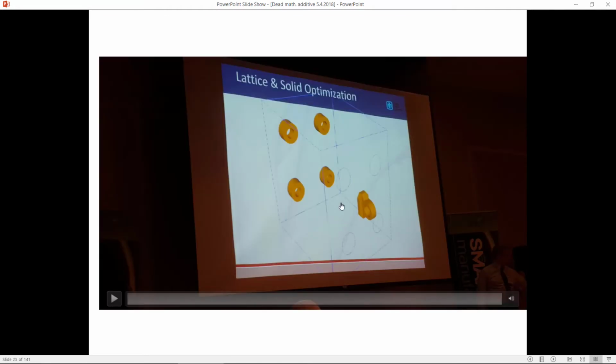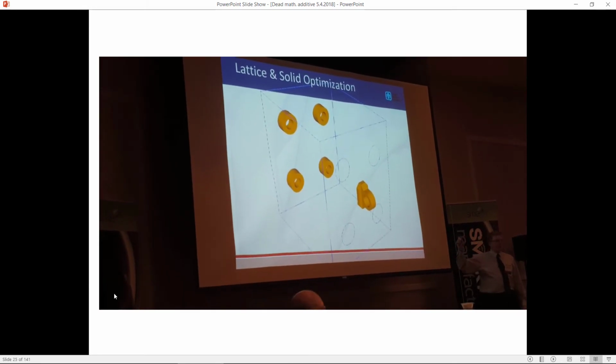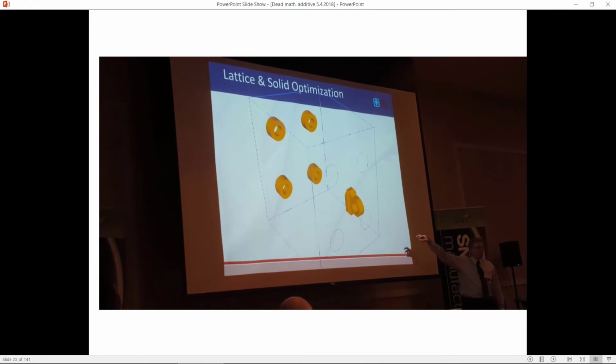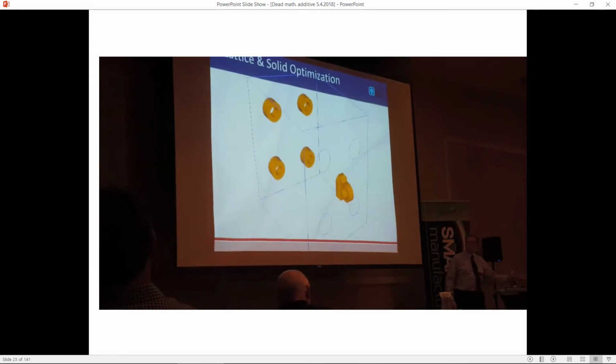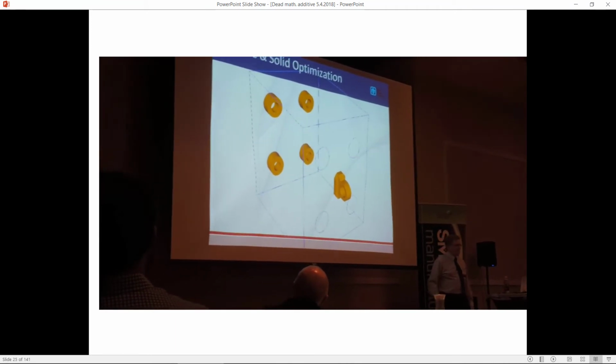So here's an example. If we need a bracket that mounts up in these 4 spots and also has this support that has a load base on it, what should this bracket look like? You set all this up, you set the material up, you set the load condition up, and then you hit optimize. Now, I don't know if you can hear this gentleman speak, but he will go through some optimization. And said, I want some solid portions so I can bolt the thing onto my test machine. I gotta have a way to put a load on that. And then the rest of it, you're open to optimize, except I need some access ports to my bolts in, so don't use that space.